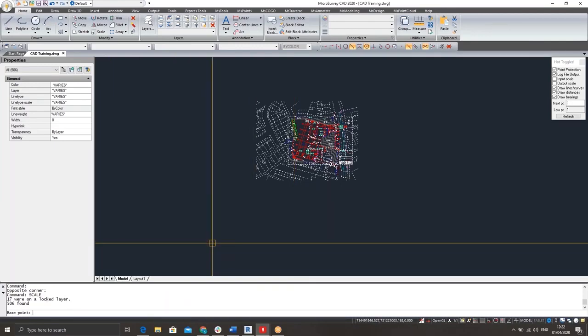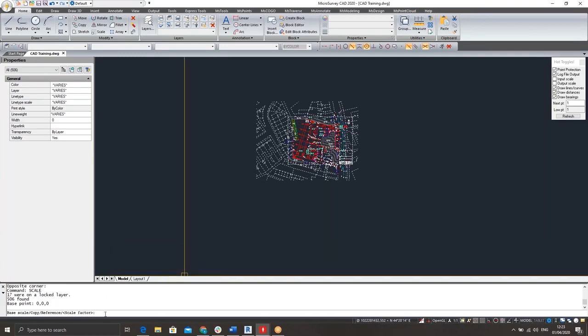When scaling, you always want to specify relative to the origin of the drawing, which is, of course, 0,0,0, using 0 ordering and obviously 0 elevation. So once we've entered that, we can select enter. And then it's asking for a scale or a reference factor. So if we want to go from millimeters to meters, it is 0.001